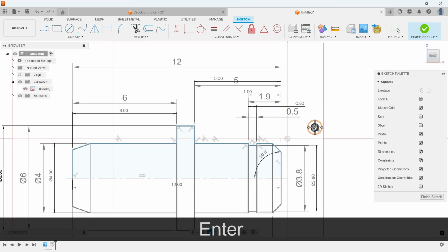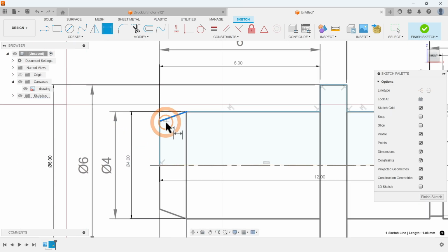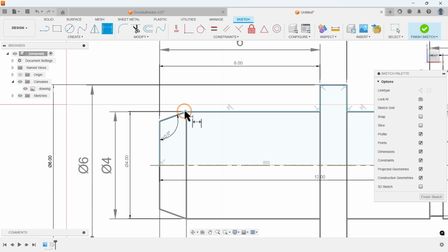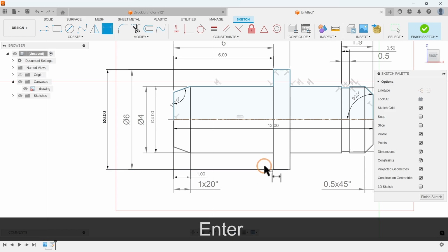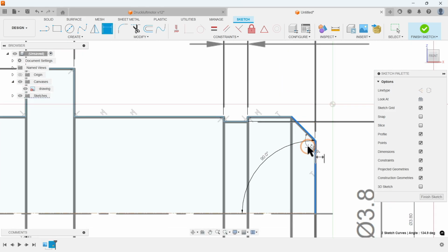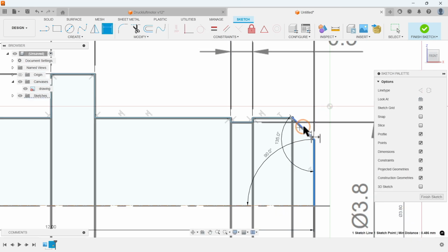We also measure the chamfers in the sketch by assigning a dimension and an angle. It should be noted that we need to add 90 degrees to the given angle. Although this is somewhat more complex than using the chamfer tool after rotation, this approach allows us to fully determine the entire contour of the tenon in a single sketch. This way, we do not need an additional element, making the construction clearer.